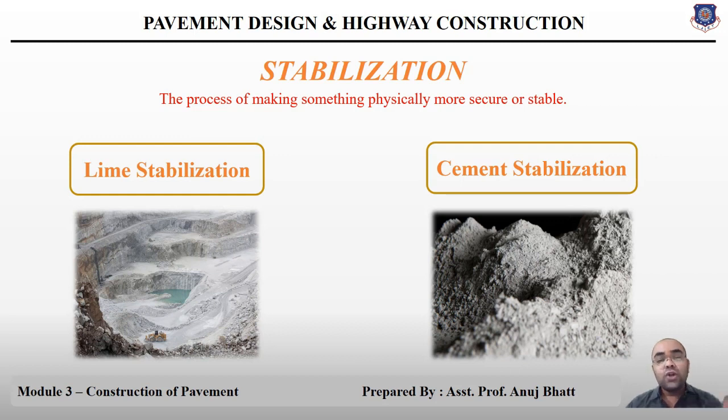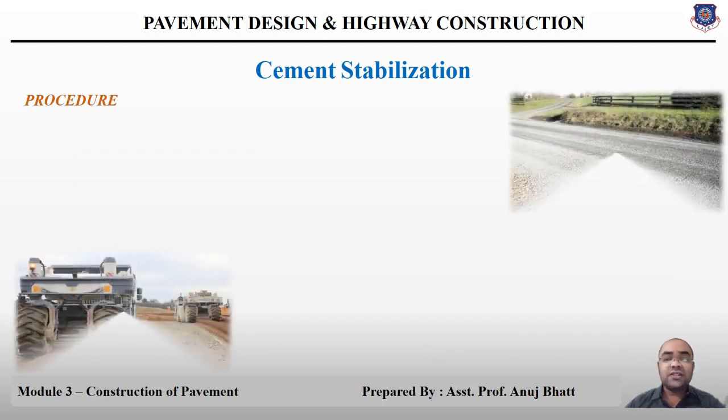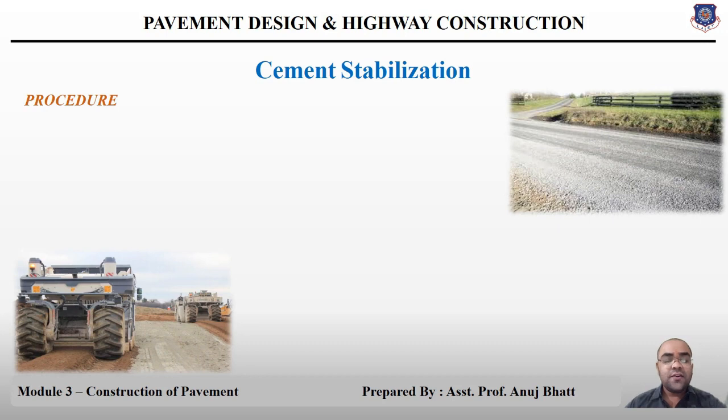Now let's move to the construction method. For the construction, at the initial stage, first of all you have to prepare a subgrade layer. In cement stabilization, an even mix is very crucial.